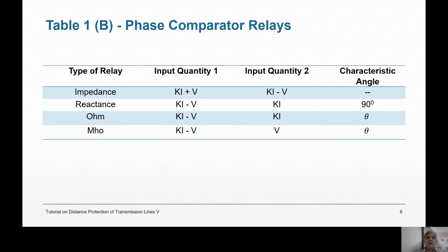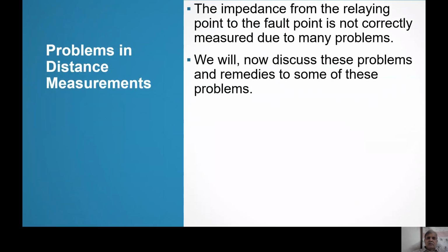And 3 currents. And if at all you want to, you can give the neutral current also. I'm saying if at all because the neutral current can be calculated by a numerical relay too, since the neutral current is IR plus IY plus IB divided by 3. That is not difficult for any calculator. A numerical relay is a computer, so it can calculate. So these quantities are fed.